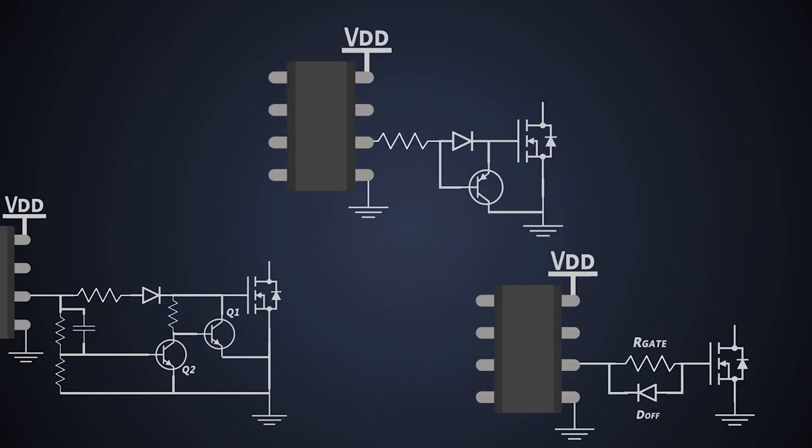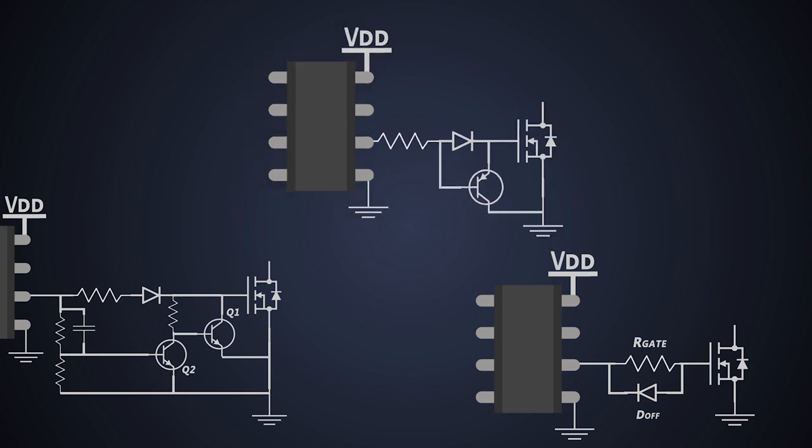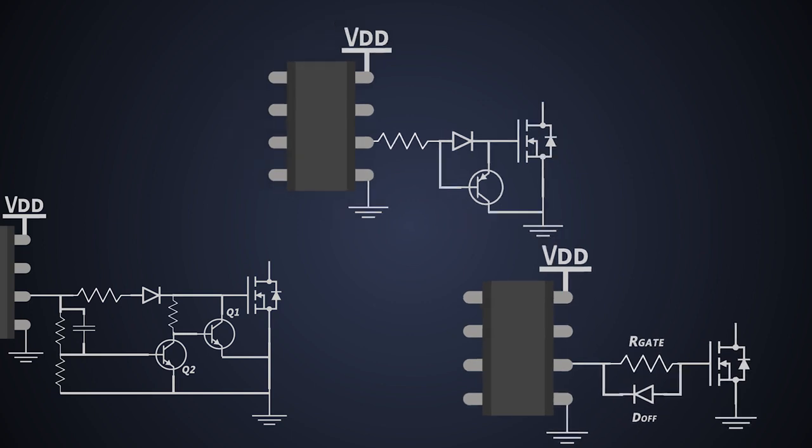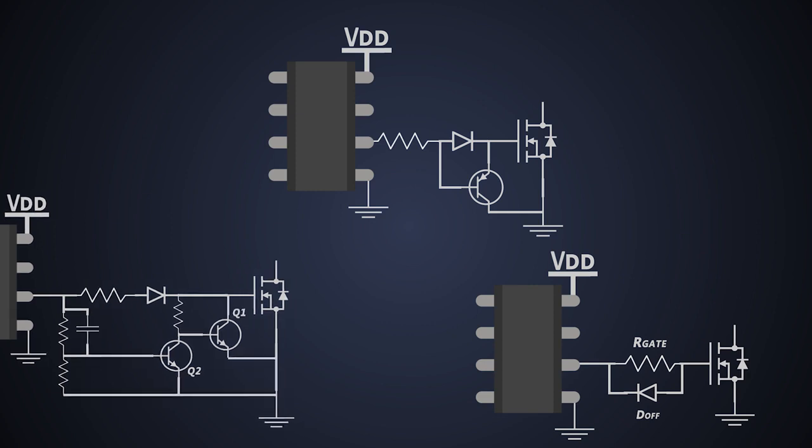So, all of these turn-off circuits which are shown here have a simple ground reference to the gate drive circuits. If we summarize all of these three circuits, the PNP BJT based solution to enhance the turn-off switching speed is the most optimum and widely used. If you want a low-cost circuit, we can just use the turn-off diode. The third circuit is complicated and has so many components. I would keep my hands away from it until it is highly required.